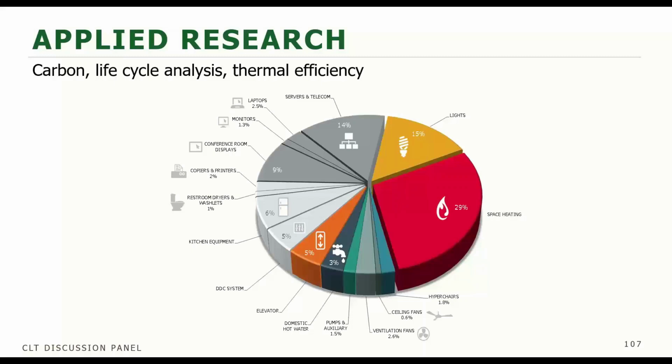During the webinar, I talked about embodied energy versus operational energy, and this depicts operational energy. So we're looking at the different contributions to energy use and therefore greenhouse gas emissions during the operation of the building. A lot of the carbon research around mass timber is focused on the other side of things, the embodied energy. So how can we reduce the energy associated with the building products themselves? And of course, wood has a really good story to tell there.